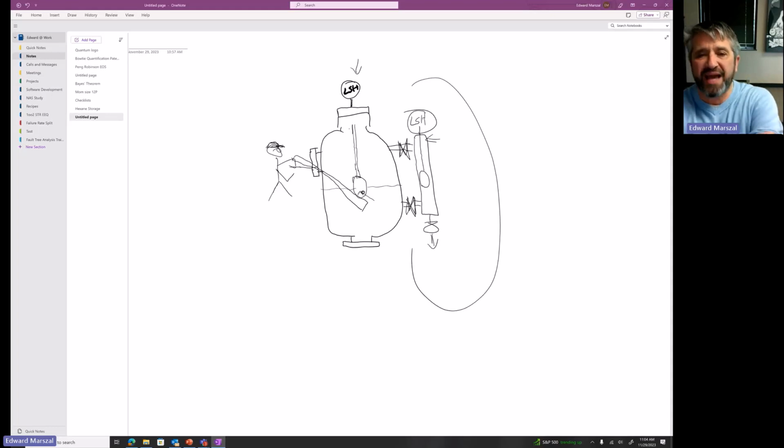So you might say that the calibrated 2x4 method of testing the level switch will have maybe a 50 to 60% chance of being able to detect a failure, because a lot of the known failure modes it can't detect. Whereas this approach might have closer to 95% diagnostic coverage, because if you have that hole in the float, you'll be able to test for it.